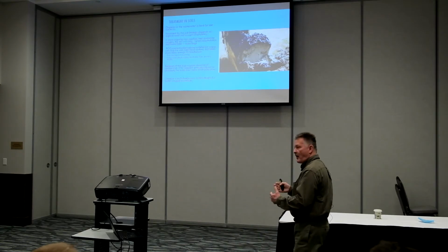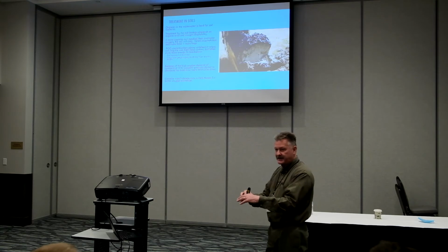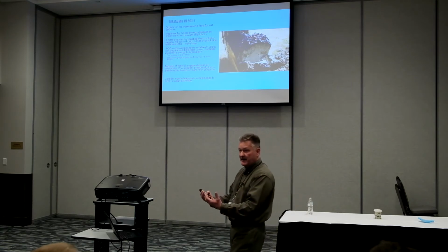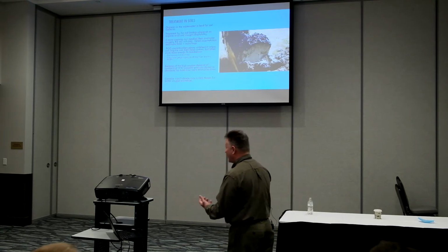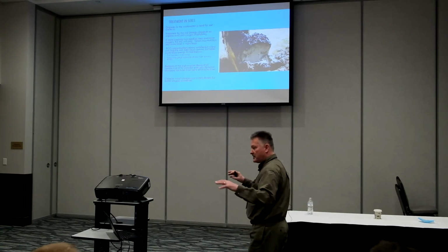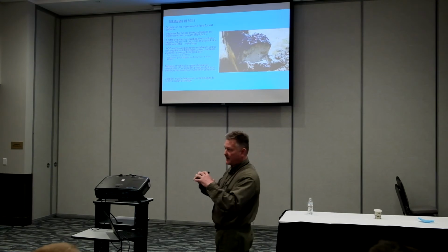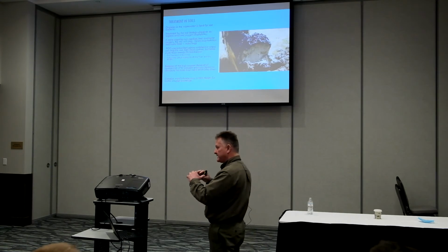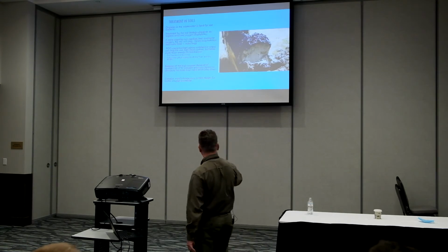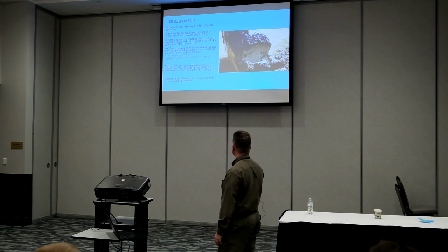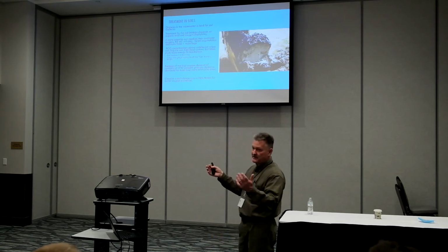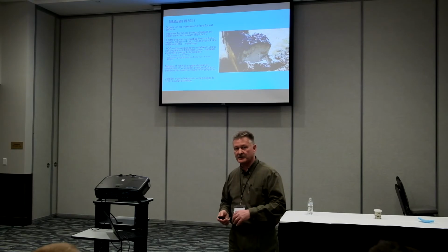So if we have more organics being applied to that system than there is oxygen available to those bugs, we're going to start clogging soil pores. The bugs are really going to multiply real quick, start turning anaerobic, start producing slime protective layers, and then we get a potential of massive ponding to the surface, which would be the regulatory definition of failure of that system.